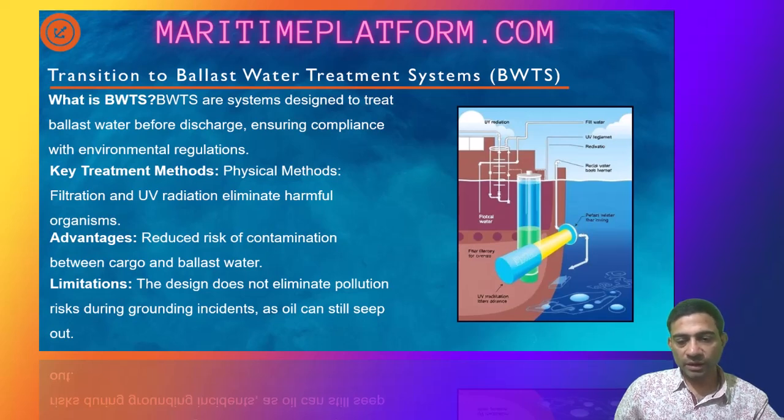Okay. This ballast water treatment system, you have to understand, it only talks about the organisms. It is just a system fitted through a pipeline, and it does not prevent any oil pollution. If the vessel grounds or has a collision which ruptures both the outer and the inner hull, still oil pollution can happen.